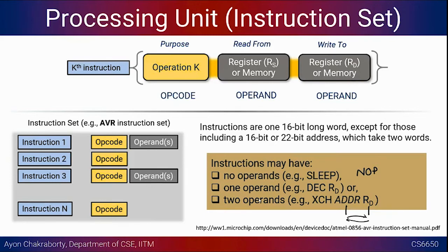But it is your duty to know what the addressing modes are, and how things are loaded. Often it could be that the register stores the address, and what you are loading is the contents of that particular address. Instead of explicitly giving the address location, because it is 16 bits wide, you might say which register stores the address.